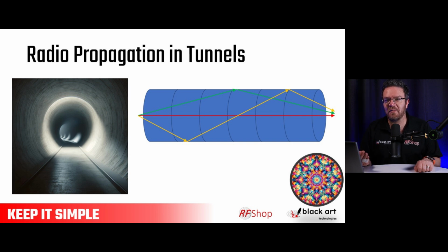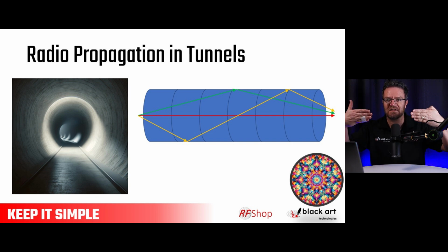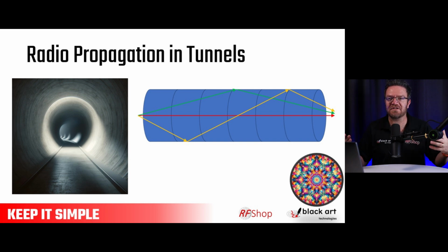And that's an antenna fundamental that needs to be used to help make this thing at least much better than using linear to linear, because if you have two antennas facing the same polarization, when I launch here, by the time it gets to this one, it's mangled into a fraction in all directions. So you lose nearly everything because you can only pick up those bits that are aligned with your polarization at the receiver end.